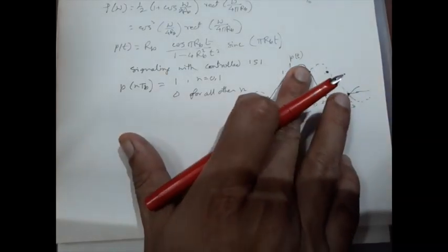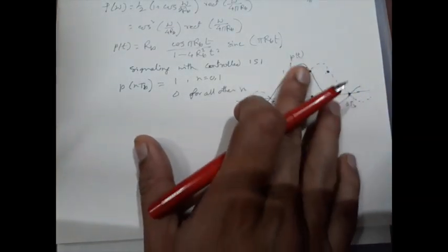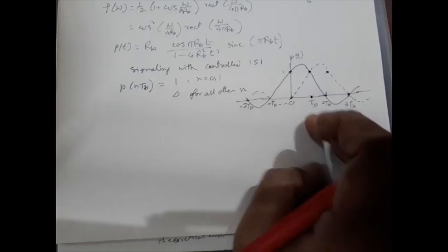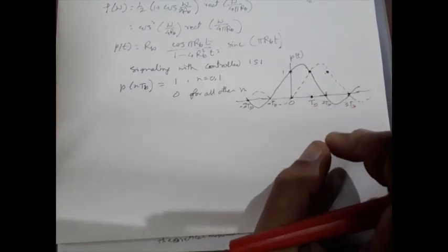Now if both the pulses were negative, then we should have -1 for the solid pulse and -1 for this dotted pulse. So effectively we should get -2. But if we have two opposite polarity pulses successively, then for the first pulse we would have 1, and for the next pulse we should have -1, resulting in 0.